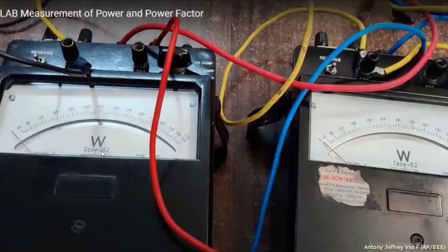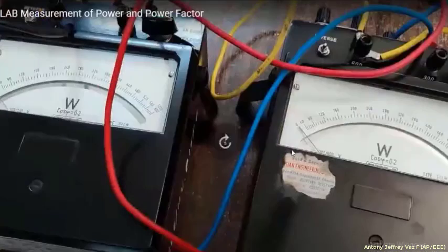This one is the inductive meter having a power factor of 0.2. You see in this wattmeter they have represented it as 0.2. This represents that the meter is used to measure inductive loads. So different meters are connected, so the multiplication factor is different. For resistive load, the multiplication factor is 4. And for measuring inductive loads, this wattmeter has a multiplication factor of 2. I will show you the inductive load.